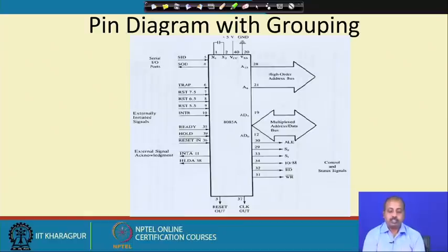Now, on my board, apart from the microprocessor, there can be many other devices that also need a clock signal. This clock out pin is actually giving the clock signal of the processor to the other components on the board. If you need any device to be driven by the same clock as the microprocessor, you can use this clock out line for that purpose.